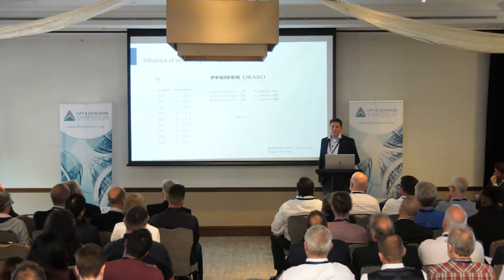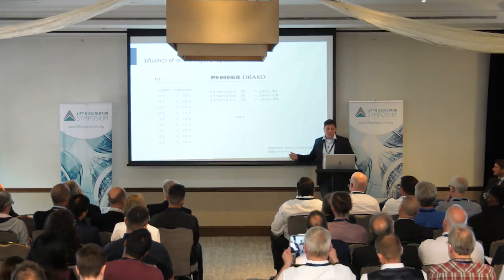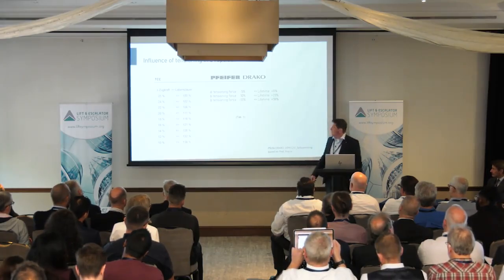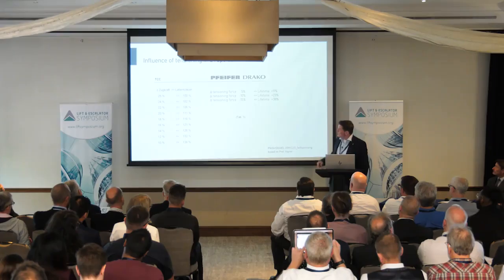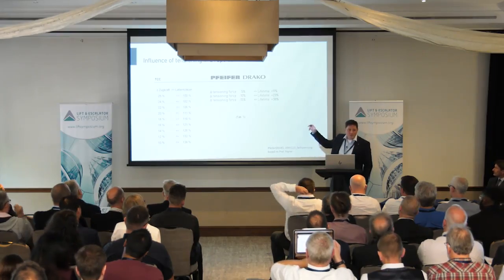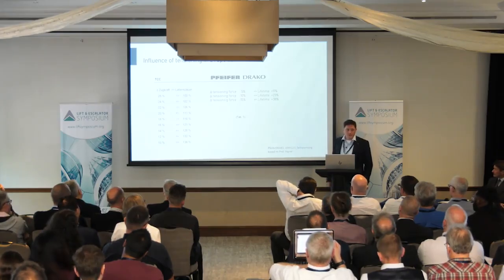So think about a lift which carries per rope perhaps 100 pounds, and the most tensioned 120 pounds, or 125 pounds to make it easy to calculate. Reducing that by 10 pounds would increase the rope lifetime significantly.